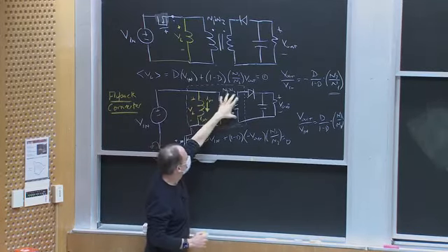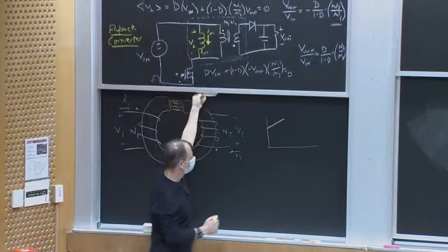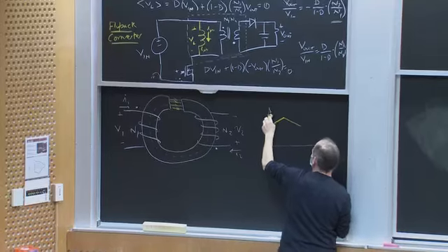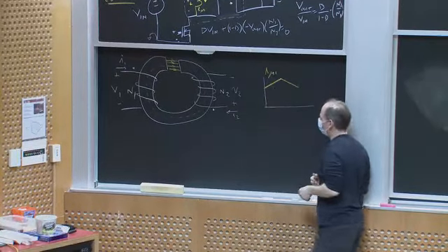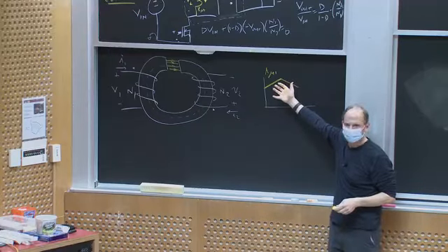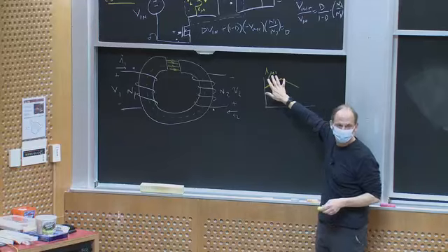Because of the polarity, the voltage gets applied and the current in the magnetizing inductance ramps down. So this is what I mu looks like, and I'll draw this as I mu1. And I'm pretending it's a 1-to-1 turns ratio for the moment. I mu1 is always going to look like this, the magnetizing current.